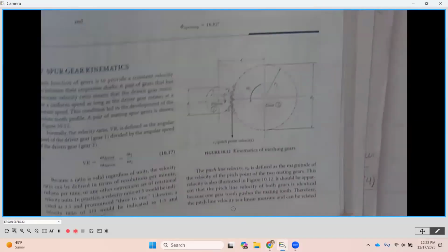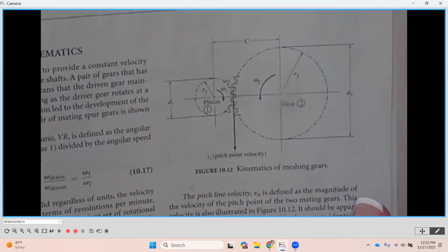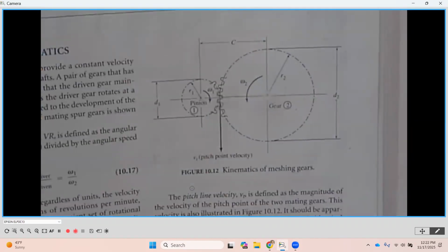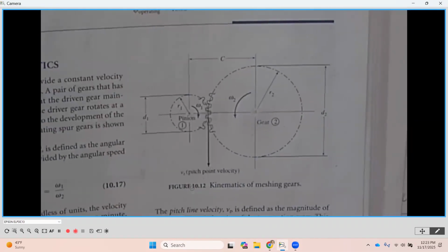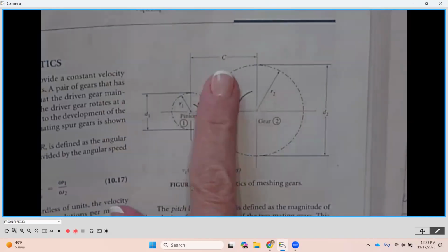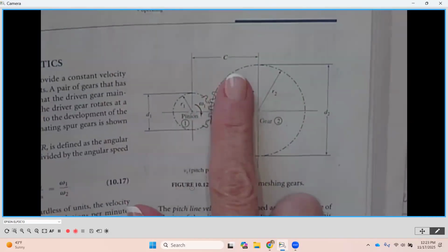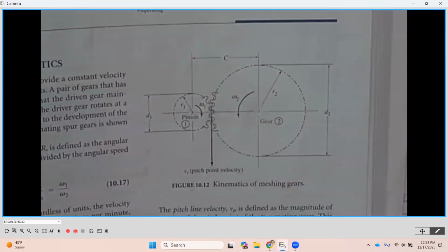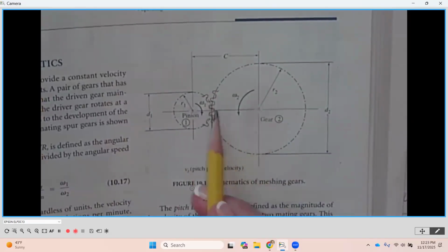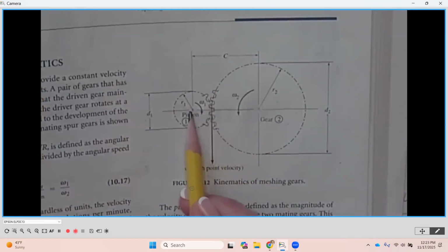And, as we physically saw some of those gears that were in engagement with one another, a couple of items are important to us, especially when we're laying out our design. The first thing that we need to be aware of is the physical size of these gears, okay? And one of the dimensions that we're always going to be looking at is the center distance between, if we look down each one of these gears, the center lines.